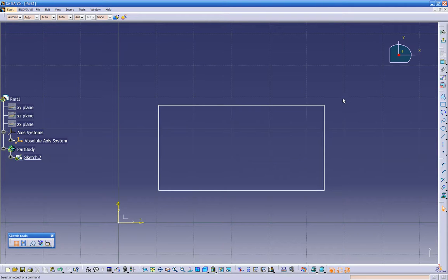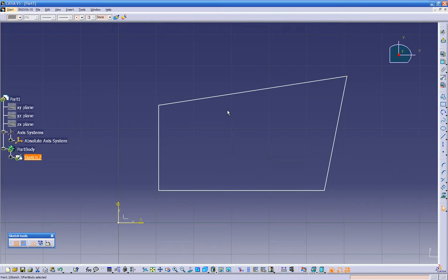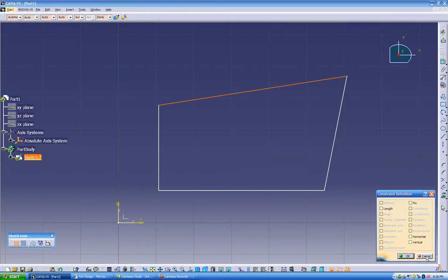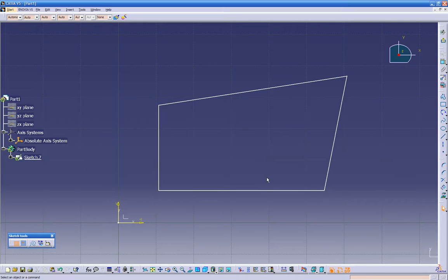Oh, before we do that, I wanted to show you this. For example, we take this over here, we can move it all over because it's not constrained onto the sketch, so we can move it. And if we try to make this line with this line parallel, it's gonna complain because it doesn't like it. So let's preset first the lines before we go into constraint mode.